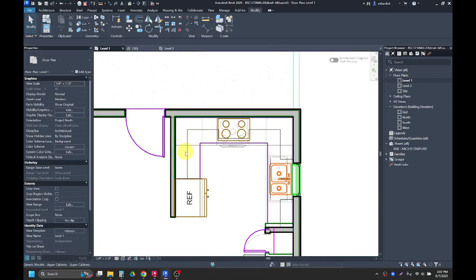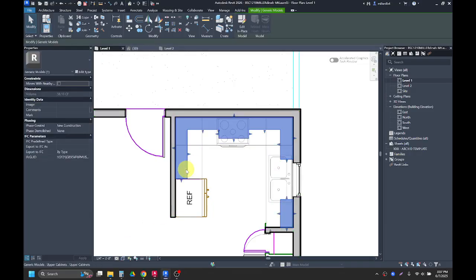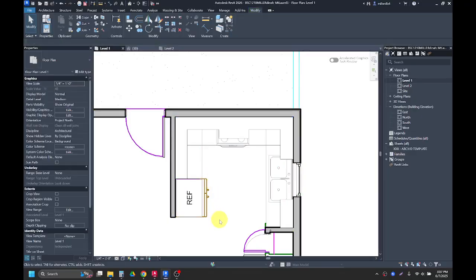They're not going to show up in my level 1 floor plan. So I'll go back into level 1 and I'll put myself back in hidden line. I was going to say they shouldn't, but it looks like they are. I was going to say just because of their height, if they're starting 5 feet up and the floor plan cuts at 4 feet.